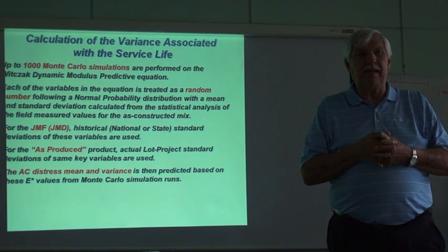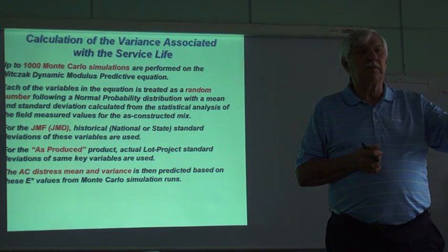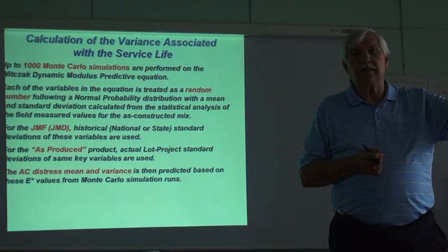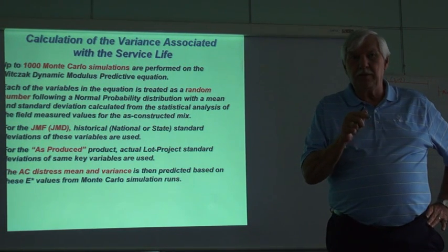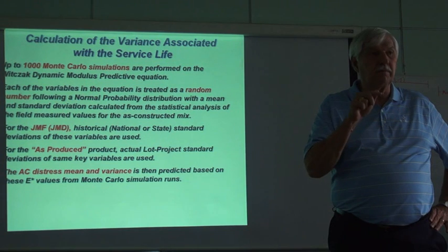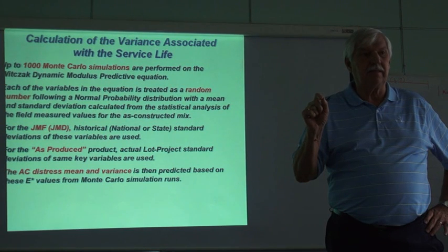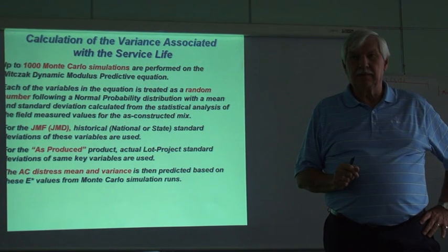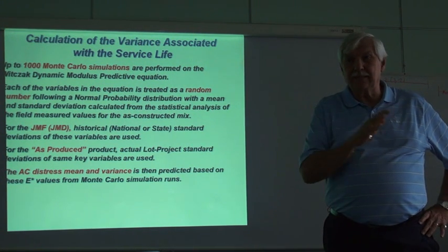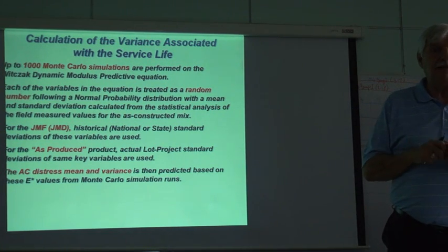And you're going to sample each one of these sublots. And as I sample asphalt content 4 or 5 times in a lot, what I do is get the true estimate of variance of what the contractor is producing. If he is exceptionally good at doing a very good uniform control on his product, he should have a standard deviation of asphalt content that's no greater or maybe even less than your national historic average. But if he's real poor and is not controlling his product very well, his variance of asphalt content in a lot may be 2 times the magnitude of your historic variance.